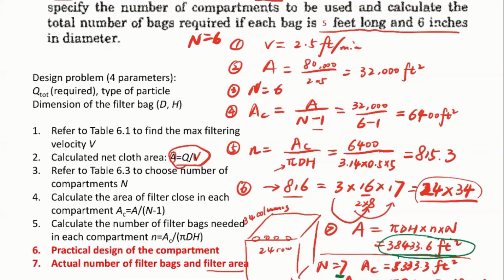After next class, I'll spend some time to briefly talk about the cost analysis for all the PM removal devices that we talked about. We can also go through some other, relatively less frequently used PM removal devices, for example, the wet scrubber. The wet scrubber is basically a combination of the cyclones and a water sprayer. Okay, so it can achieve slightly better particle capture efficiency compared to the cyclones, but they're generally more expensive than the cyclones. So we can talk about that mechanism.